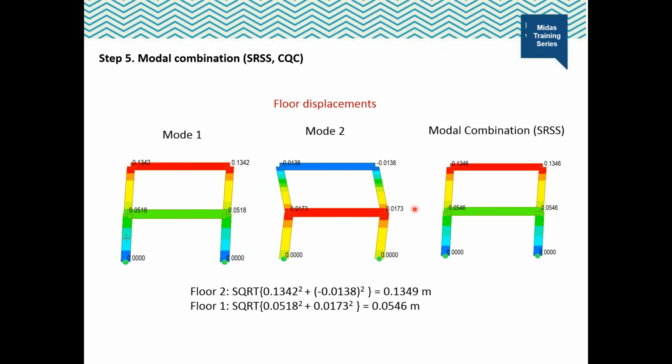As the final step, determine an estimate for the peak value of any response by combining the peak modal values according to the SRSS rule or CQC rule, because unlike mode superposition method with time history analysis, the peak modal values in response spectrum analysis are not concurrent results. The CQC rule should be used if the natural frequencies are closely spaced.